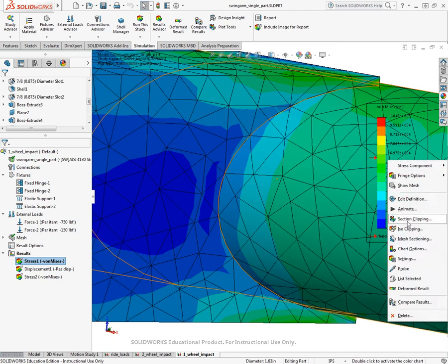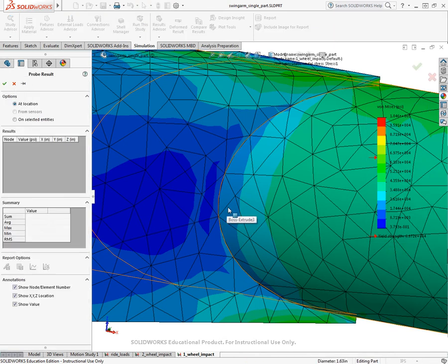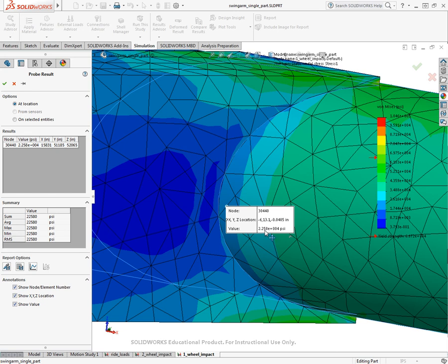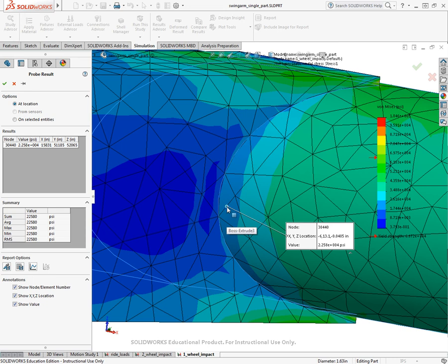Exact same node. I think it was that one. Yep. There we've got a stress of 22,580. So those three stresses, and I've forgotten what they are, can be used for one application of Miner's rule, which will determine the total life expectancy at that point.